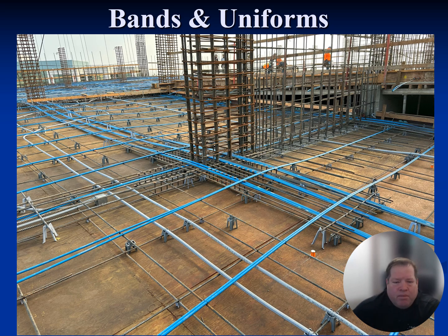This is another example of a two-way system. Again, minimal rebar. You can see there's rebar at the top of this column support here. This is actually the jamb of a shear wall. You can see here there's a shear wall right there. Again, the same general profile. The banded tendons go right over the column or embedded column in the shear wall, then start draping down and go back to this particular column. Uniforms go over the top, no interaction, simplicity of construction.